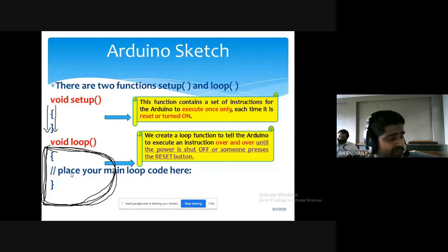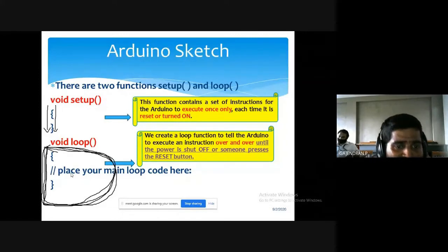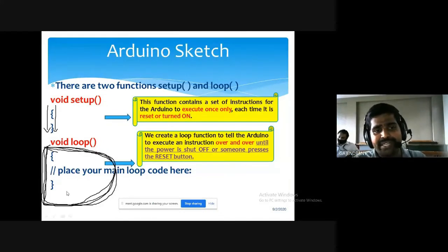Then at 4 or 4:30 we will go home again. At that time, if I show the hand in front of the system, it has to give the sanitizer, isn't it? So 24/7, whenever you power it, it has to work. So that code I need to write in void loop. So void loop is nothing but while of 1, this loop will get executed infinite times.